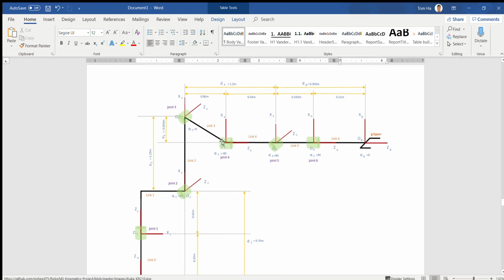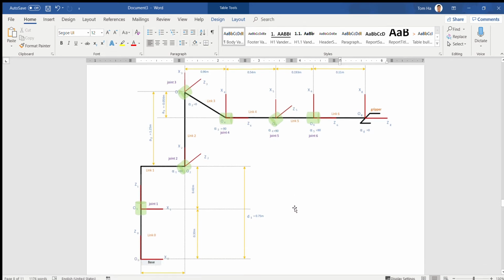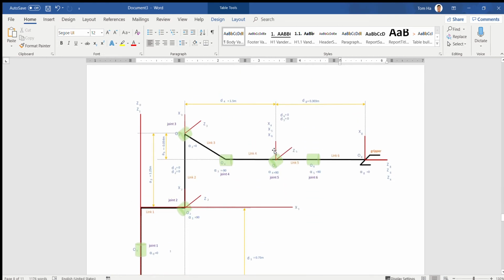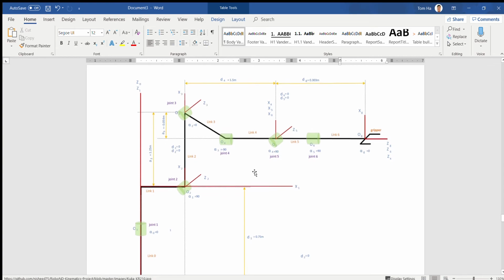And as I mentioned before, joints 1, 2, 3 create a spherical wrist, so we can combine the three coordinate frames into one at 5. Here at 4, 5, 6, and you see that from the table, D4 is right here, the total distance from here to here.